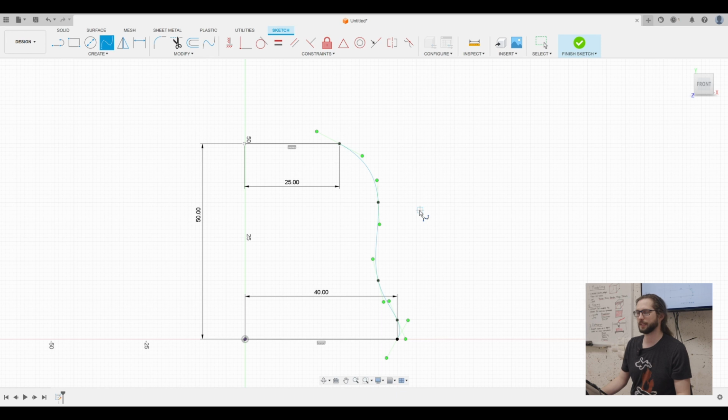If you are editing a spline, it looks complicated, but what is actually happening is that these green handles just let you change how much it's curving. And finally, I'm going to put just a straight line down the center of this to close in this sketch. So it automatically closes? It won't automatically close. Sorry. There were only 3 lines here before I put in that 4th line, right? This one, and this one. Once you close it, so that 4th line, it turns blue.